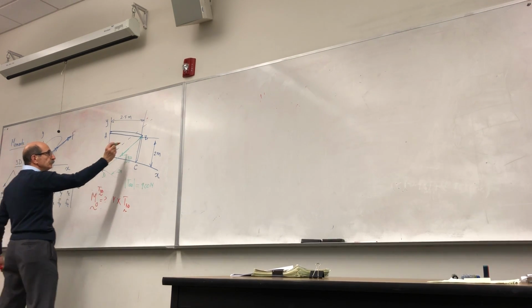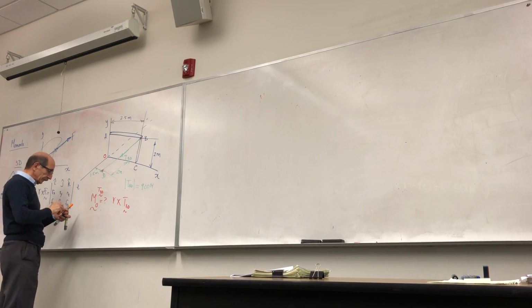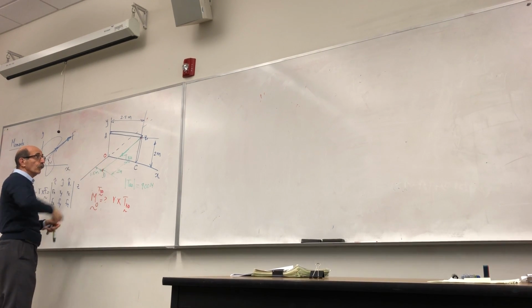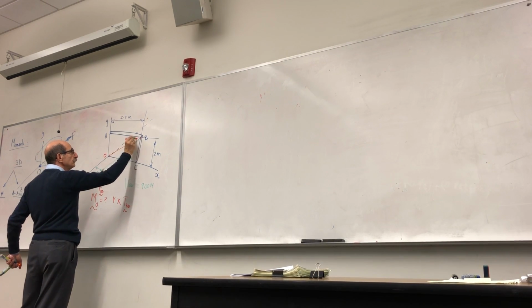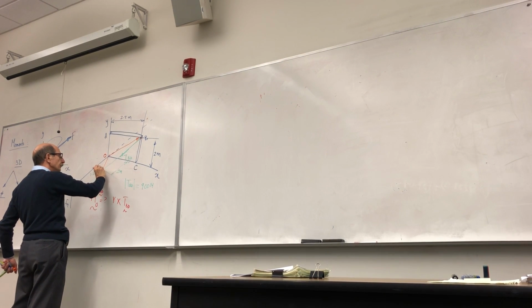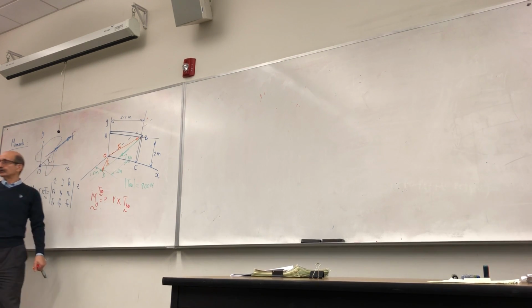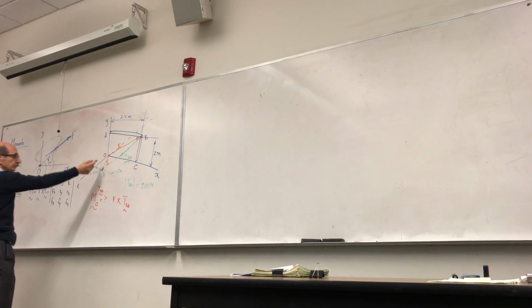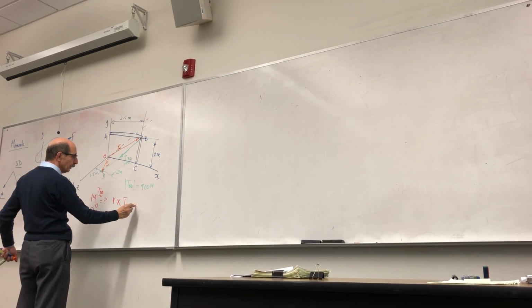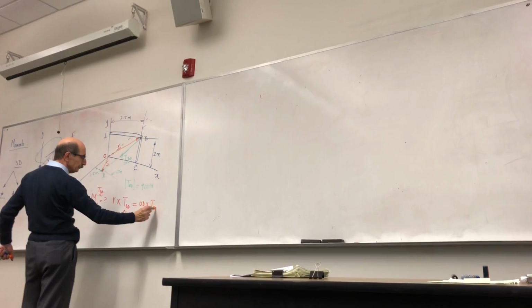Obviously, you're only given coordinates of 2 points along this force, so you need to connect that point to either this point, you have two options, or this point. Either of these two can be used as the position vector, doesn't matter. I choose OD, so I would write OD cross T_BD.